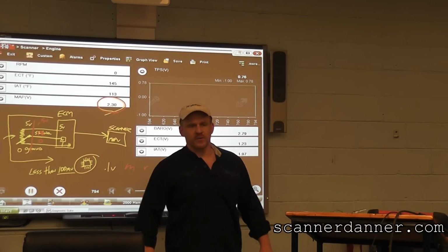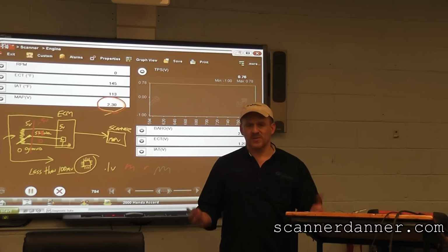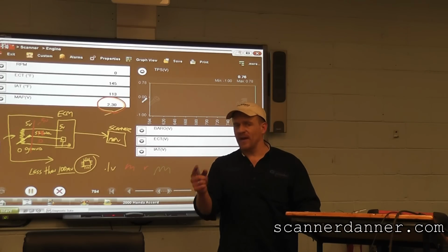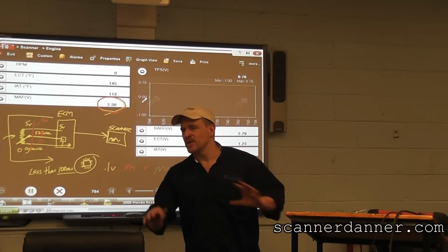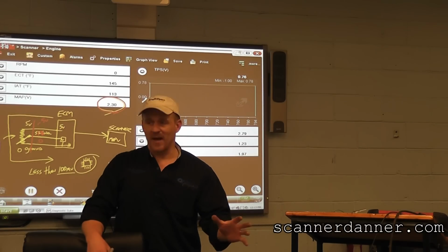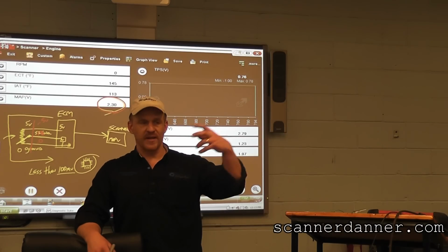And I'm pretty sure that was the wiring. Here's the thing. What I see on the sensor doesn't match the scan tool. And when you see that, you have either a wiring problem or a computer problem, not a sensor problem. So right there is where I paused and I said, okay, I can't show you the quick methods I want to show you to verify wiring integrity. We're going to need a diagram.